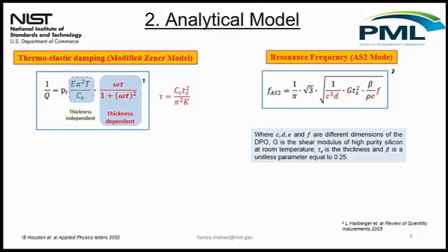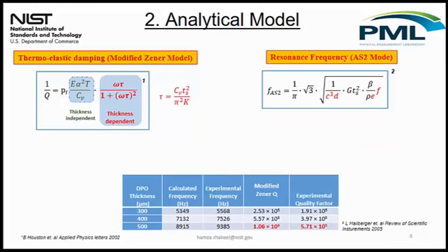So once we move to the next stage where we are planning to optimize its geometry, what we see from this particular expression is that CD, for example, is the dimension of the head. So we have room to shrink the head of our oscillator. That is going to help us increase the quality factors further.